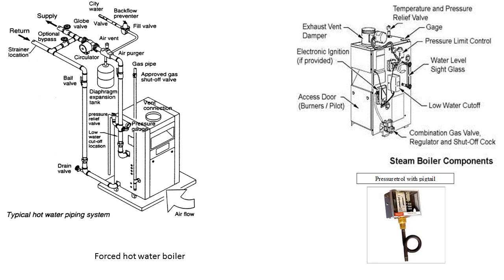That means it not only does the boiler contain water, but also all the piping is full of water. This gives the water a place to go when the water is being heated and expands in volume. Forced hot water boilers also have circulators. Circulators create a difference in pressure to help move the water around the system.